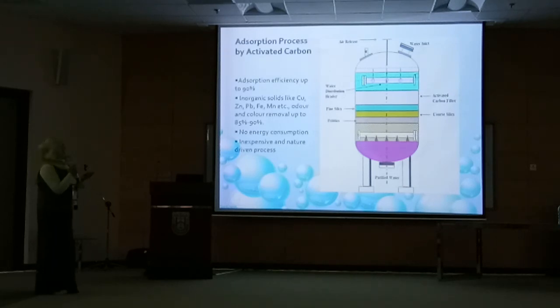We choose the adsorption process as its efficiency is 90%. Inorganic solids like copper, zinc, lead, iron, manganese, and odor and color removal up to 85% to 90%. This process is like the filter you use at home, so no real energy consumption for this, and it's inexpensive and a natural driven process.